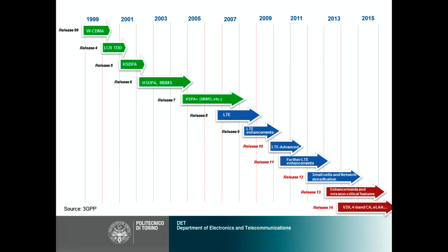So whatever resources they are using in a restricted cell may be reused in nearby cells. Network densification is all about having small cells coexist with larger cells and reusing resources in nearby areas through low power transmission, and in this way you avoid conflicts between resource blocks operating on the same frequencies.